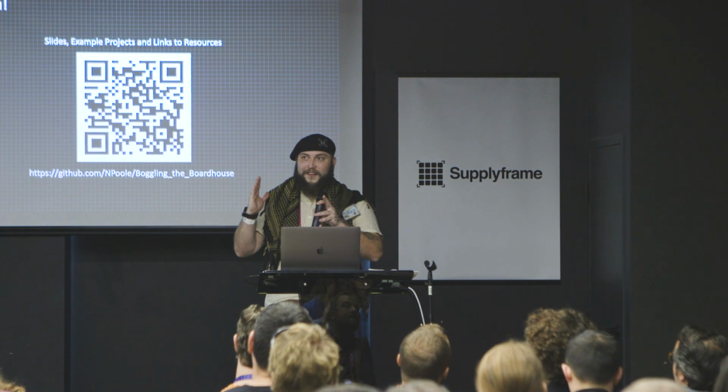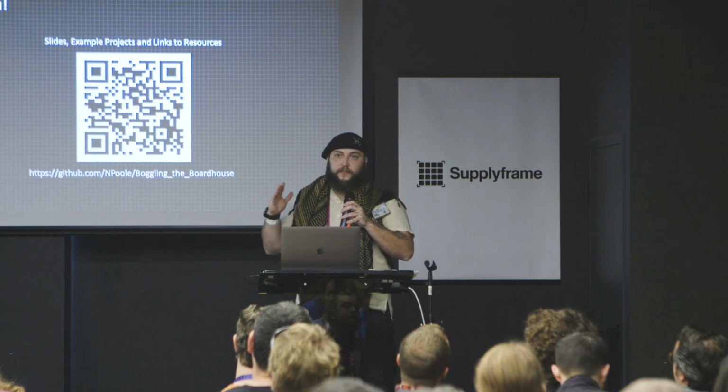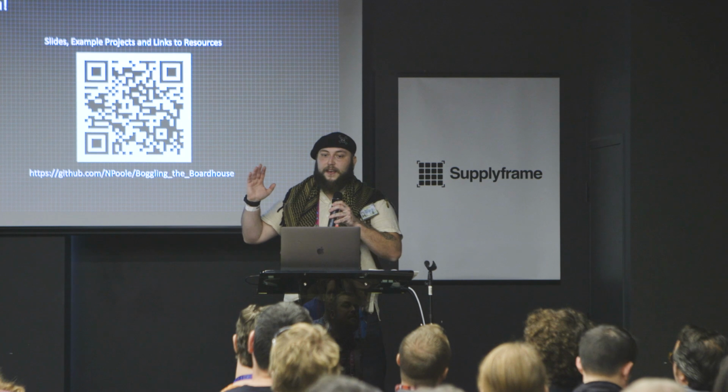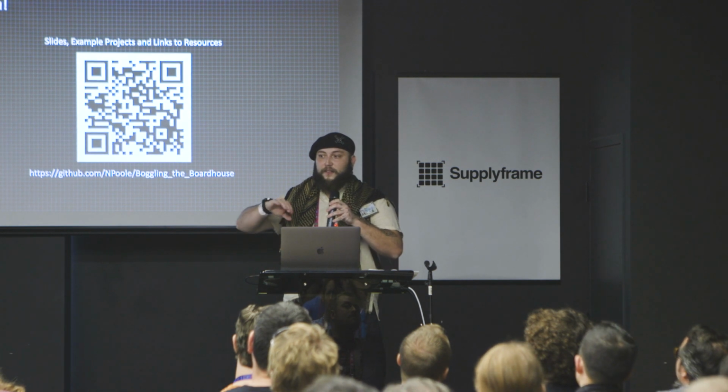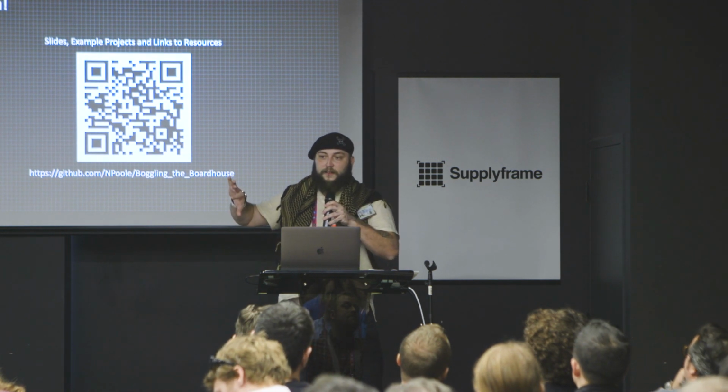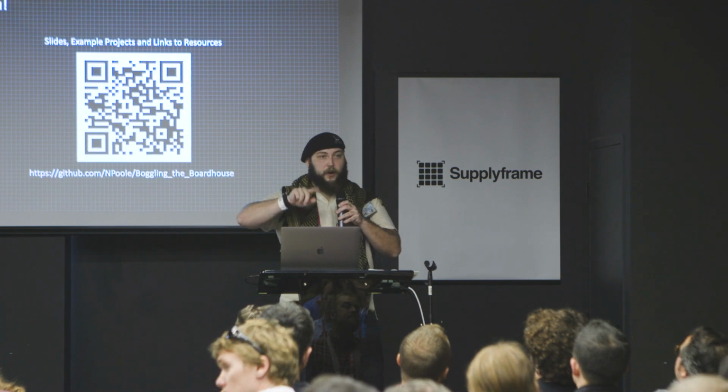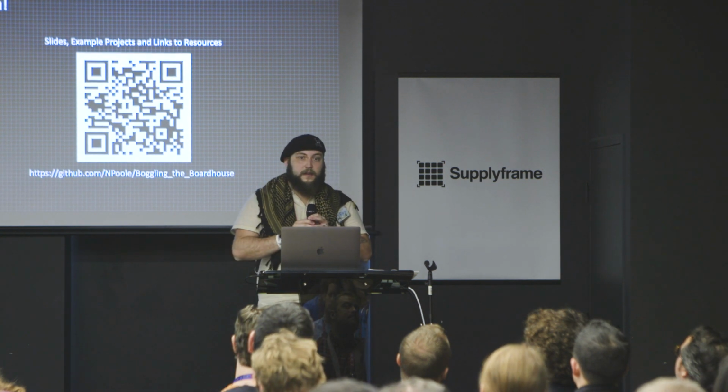spacings very small. Generally I'll go into my design rules and turn off isolate and make it 0 mil so that everything runs straight up against each other, and then I'll go in and explicitly mark where I want keep outs to be.